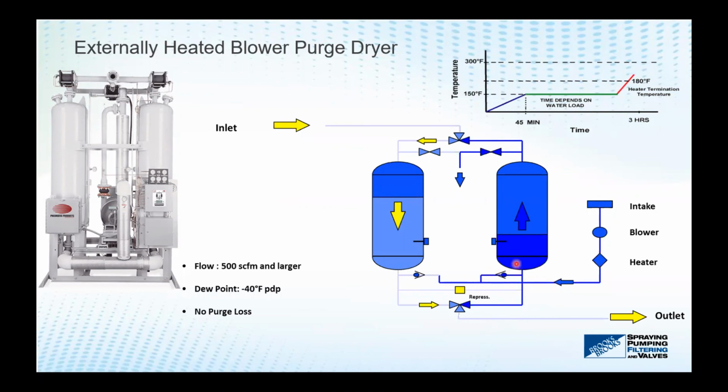So what we have to do in that chamber, and if you look at the diagram just above the schematic where it shows temperature rising from 0 to 150 degrees F, what we're doing there is we're heating up the steel of the vessel, which takes so many BTUs, we heat up the desiccant, which takes so many BTUs, and then we need so many BTUs to drive off the moisture, and that's what's happening as we pass down that green line.